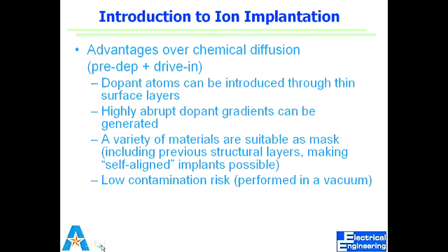So can you avoid the bird's beak like this? Pardon? A bird's beak. The bird's beak that forms between the source and the drain. Can it be avoided completely by this, or will there be some effect? Bird's beak is formed in silicon dioxide. But since you are defining a vertical trench, can that be eliminated using this method? Sort of, we're not creating any trench. There's no physical removal of material here.